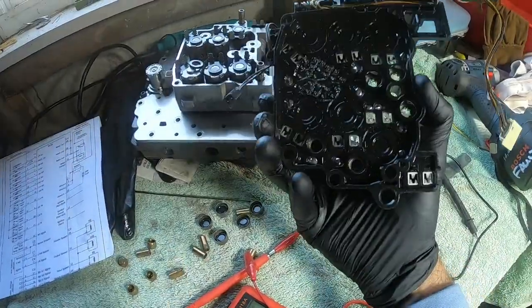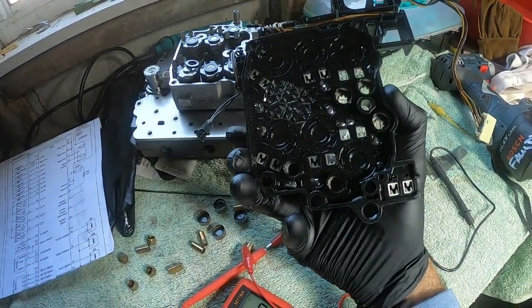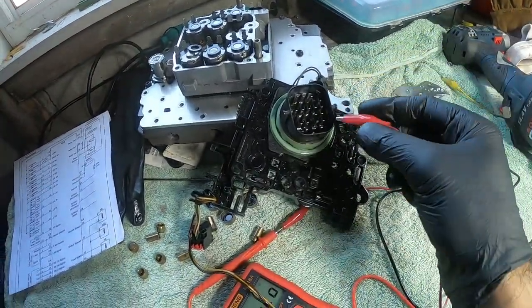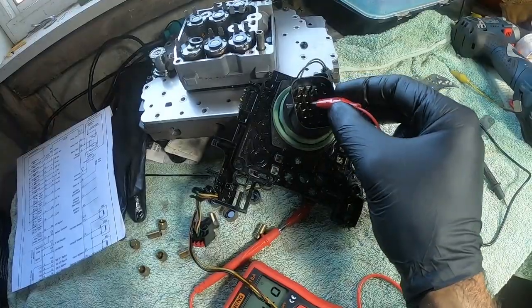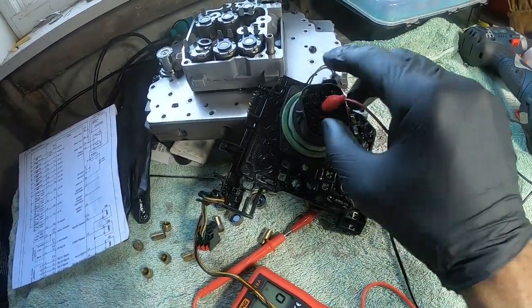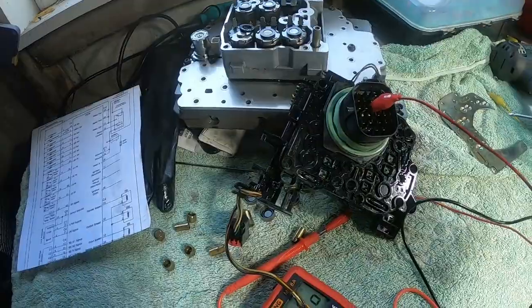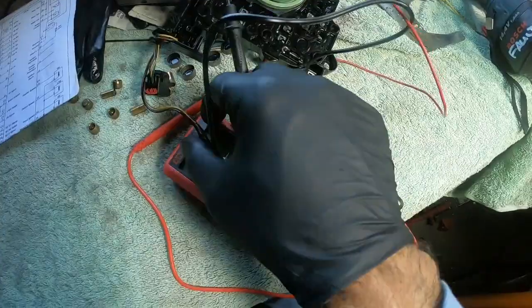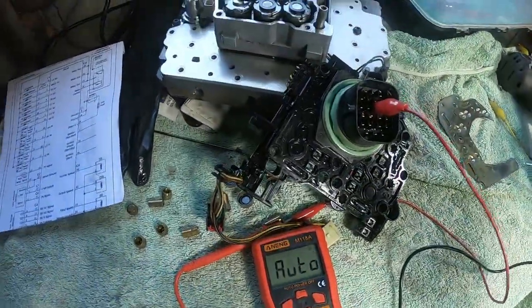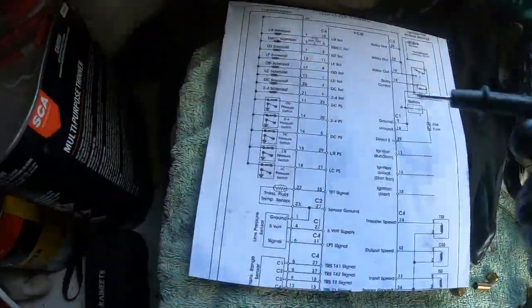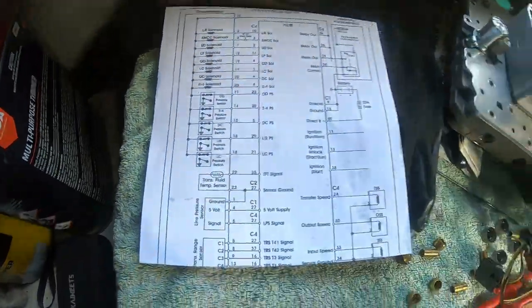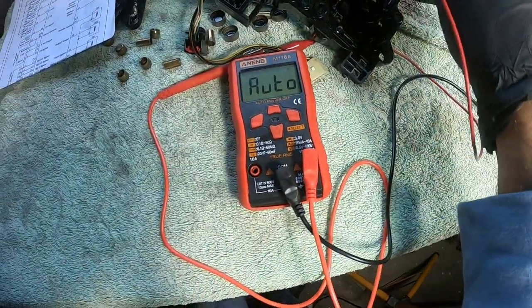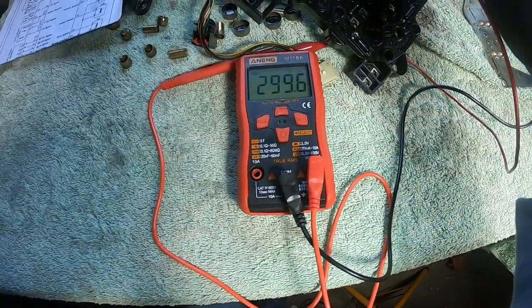Now note that these are not connected. There is just the contact. So the way it works is that the power supply goes from pin number 10, counting 1, 2, 3, 4, 5, 6, 7, 8, 9, 10, and then it goes to the pressure switches, which are currently not connected. So it should show around 300 ohms. So the pressure switches that we have are number 11, 14, 15, 16. Right next to 10 is number 11. And there you go, 300 ohms.